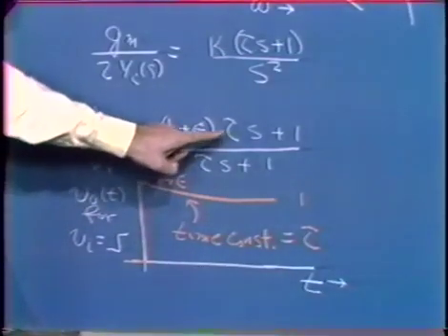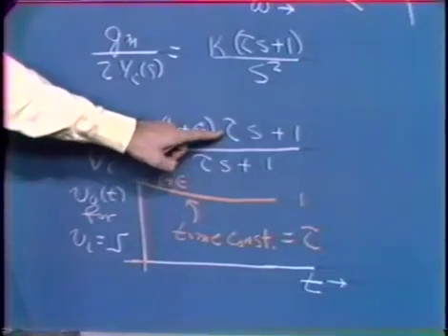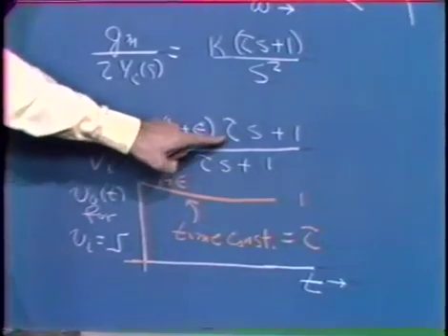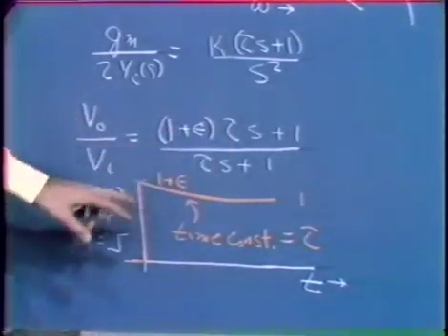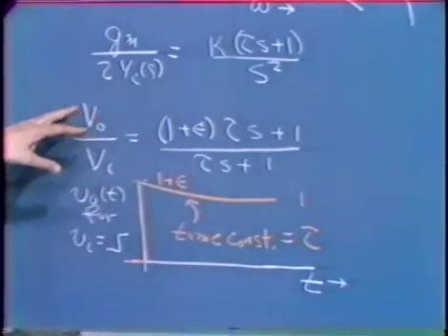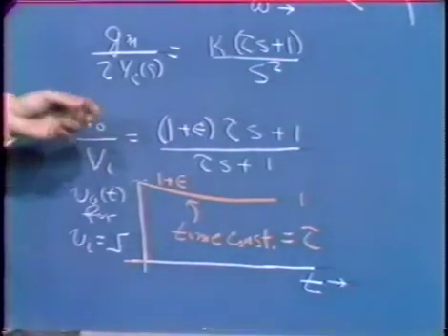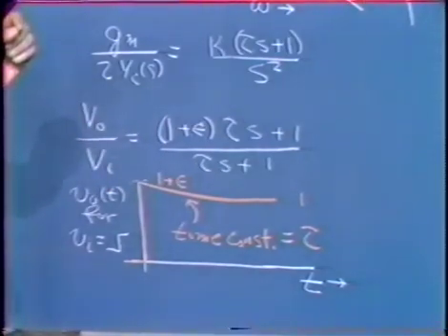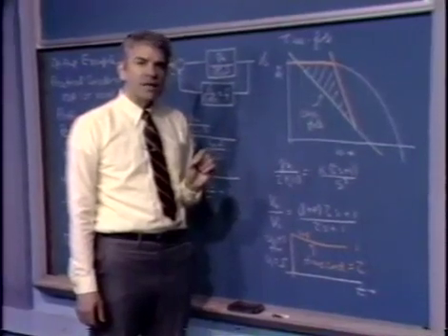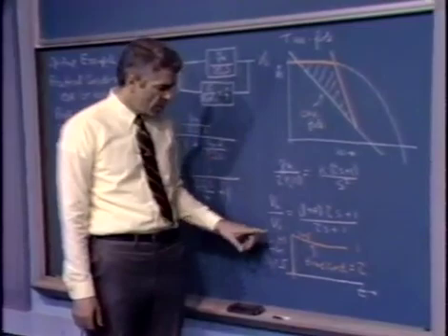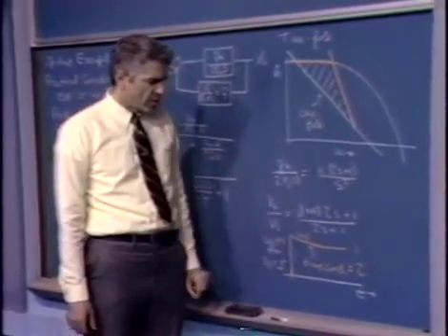Epsilon's a small number. As the situation was shown in the view graph, we have a 0 at a somewhat lower frequency than the pole. So we can visualize the system as being one that gives us the step response corresponding to the dominant pole pair, but we view that step response through a filter that has this transfer function.